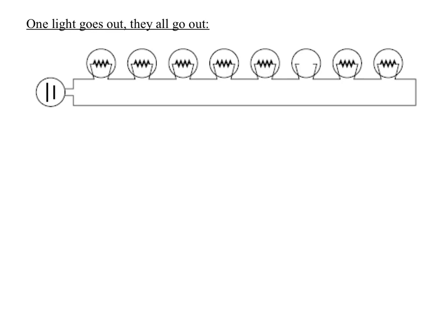When lights are strung in series, if one bulb goes out, all of them go out, because the circuit is now open. When that bulb dies, suddenly that charge, although it's being pushed forward from the positive terminal, cannot go continuously through here. It can't just jump that gap and end up over here. Because there's a break in the actual circuit, that's an open circuit. So in series, if something burns out, whether it's a bulb or a resistor, the entire circuit will stop operating. So you can see the limitation of a series circuit already. If one thing breaks, the rest of them aren't going to work.